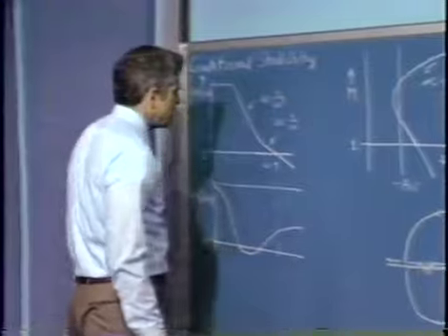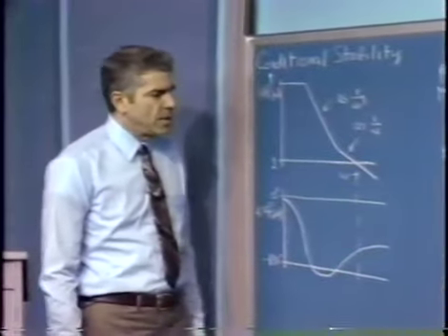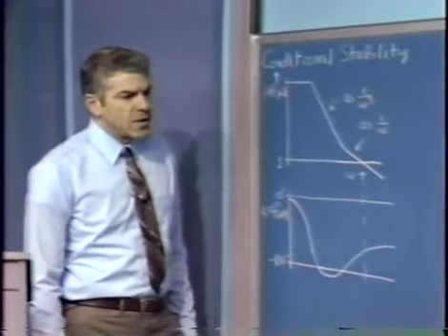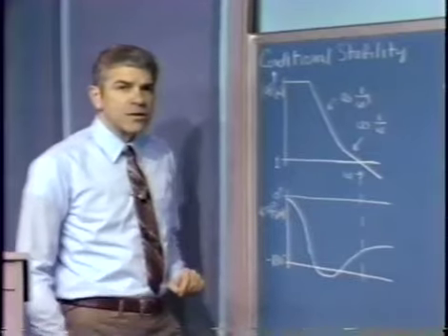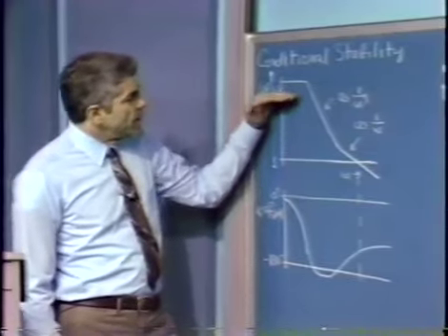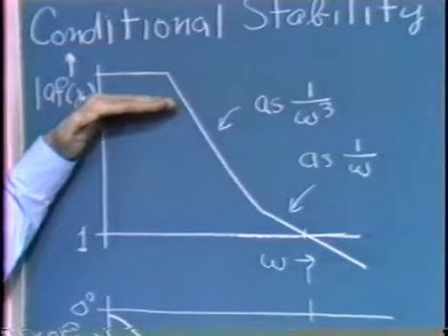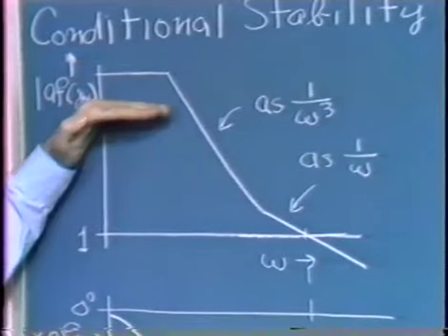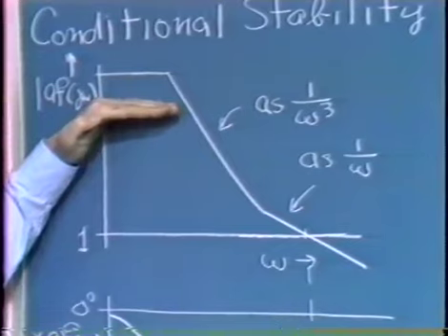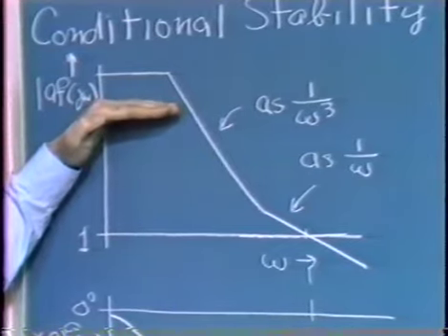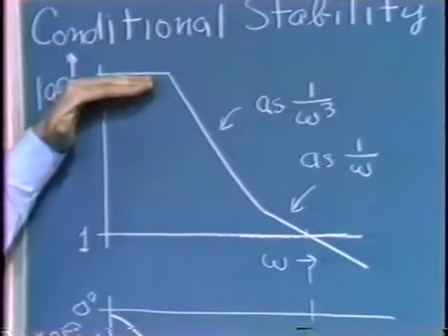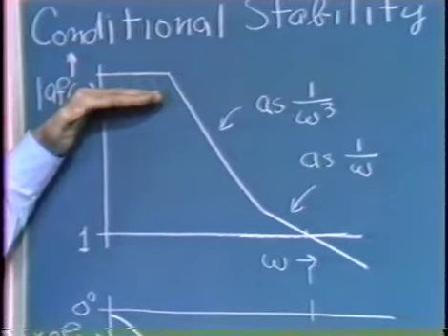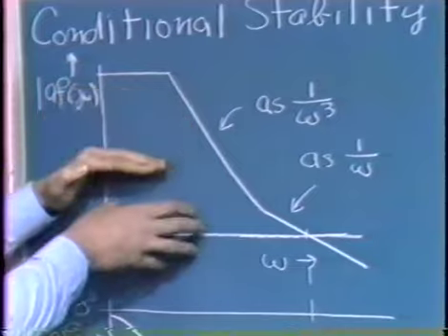Consider what happens if the amplitude of the signal applied to the nonlinearity is such that we're into the saturating region. And if we now consider this to be a plot of the negative of the loop transmission for a nonlinear system, where we, of course, get the gain of the nonlinearity via our describing function analysis, we'd find out that operating in saturation shifted the curve down.